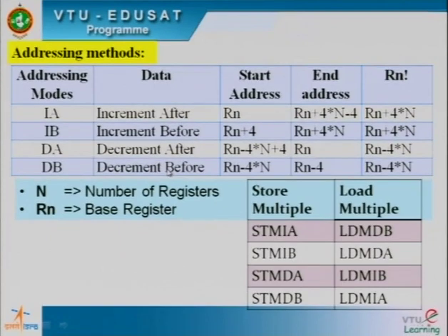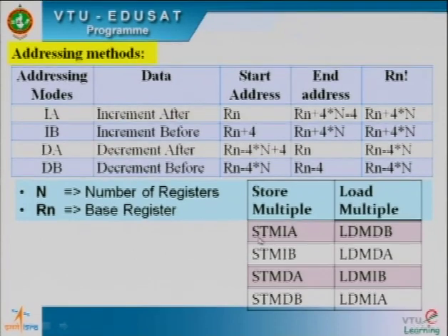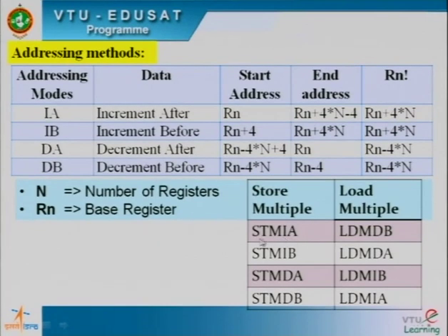What is the significance of this? See the store multiple and load multiple instructions. We can write the instruction like this, STM IA, that is store multiple register values, and increment the memory location after storing it. STM IA stands for store multiple increment after. What is the meaning of this? Store multiple register values onto the memory and then increment it. LDM DB, what is the meaning of this? Load multiple register values from the memory and then increment the memory location. We will take examples particular to these addressing modes or instructions, where it will be more clear. Before going to this, let us look at this table again, the top table.